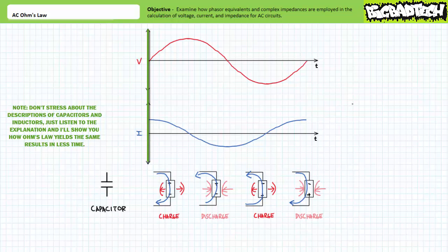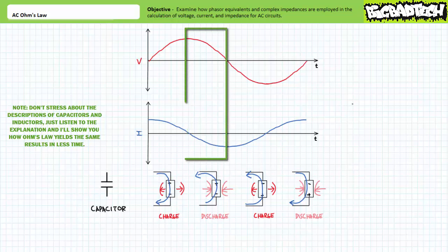When the capacitor is uncharged, i.e. has no differential across it, current rushes in and is respectively large in magnitude. During the charge process, an increasing voltage differential develops across it and current subsides. When charged, i.e. has a large differential across it, current stops. When discharging, current flow reverses direction and the voltage differential drops.